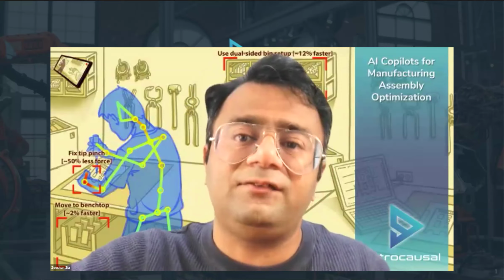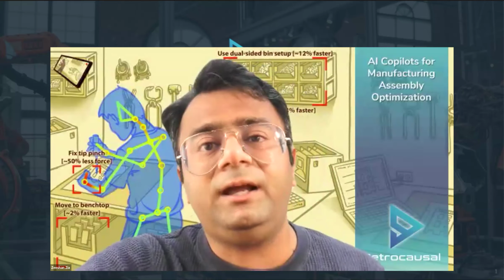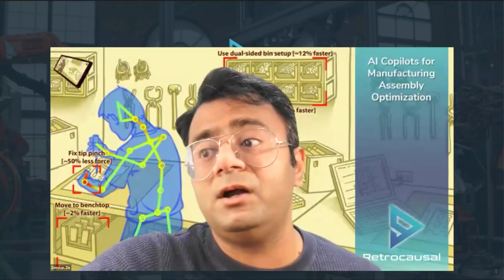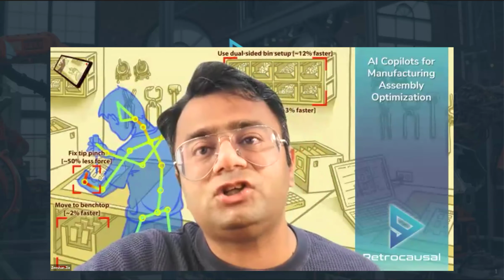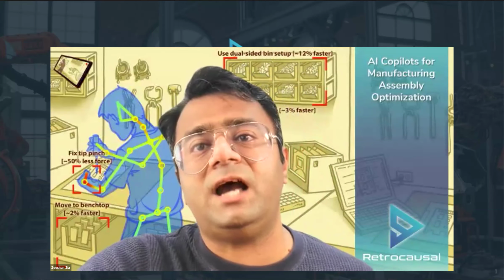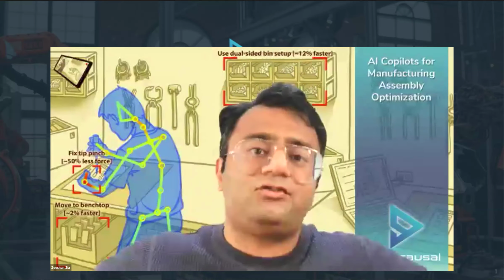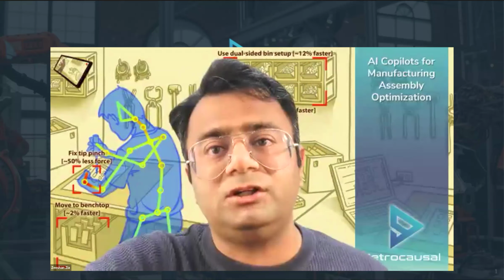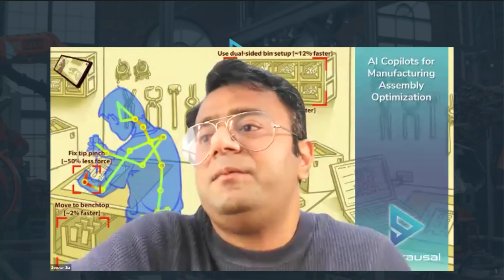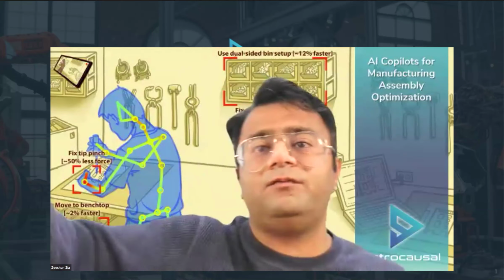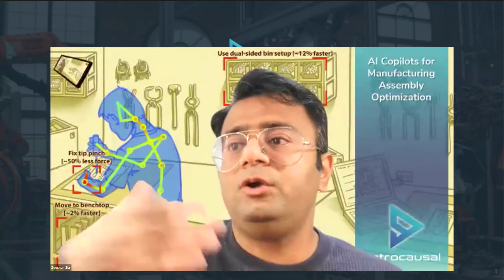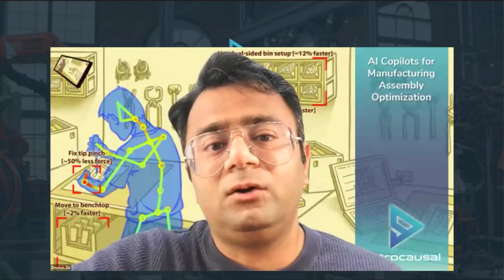Of course, there might be things that you just cannot model in the system. For instance, if right now I have 5 stations, after the line balancing, I will have 3, and maybe I have the same operator working 2 of those stations. How do you get the walking time, right?